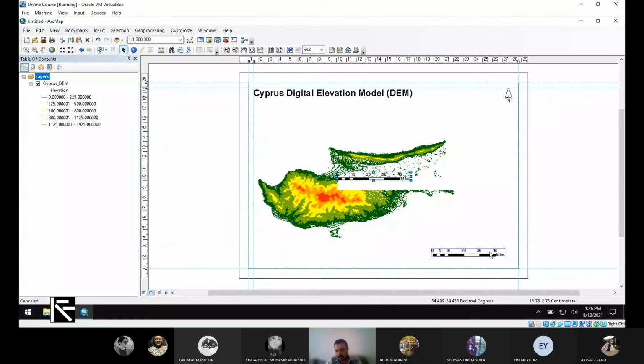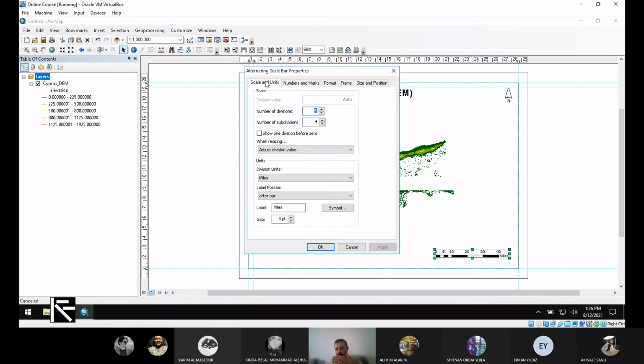Because the scale as a text, if you enlarge your paper later, the scale is not changed in the map as a text, but in reality the scale of your paper is changed if you enlarge your paper size. For instance, if your design is in, let's say, A4 layout, and then you print it out in A3, your map scale increases and becomes twice. But if you write just 1/100 there, it is wrong.